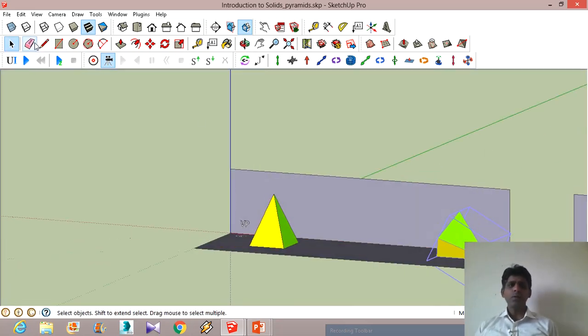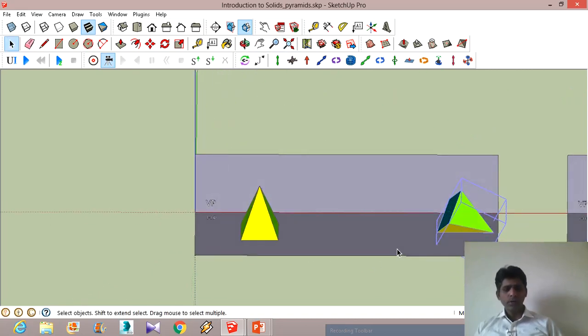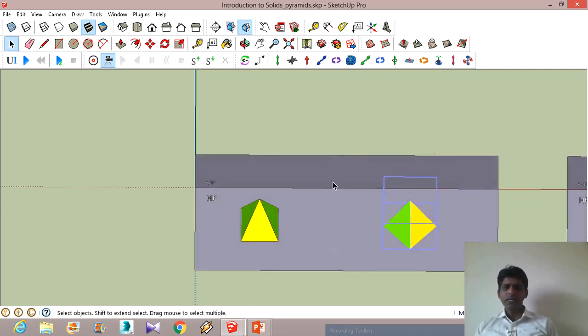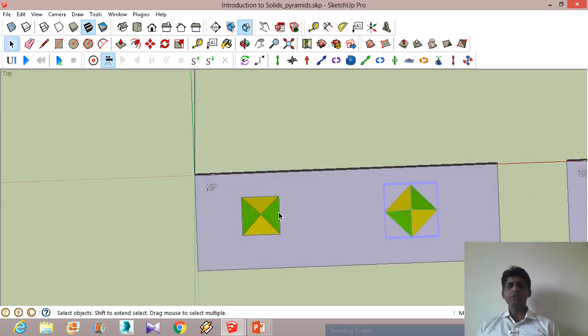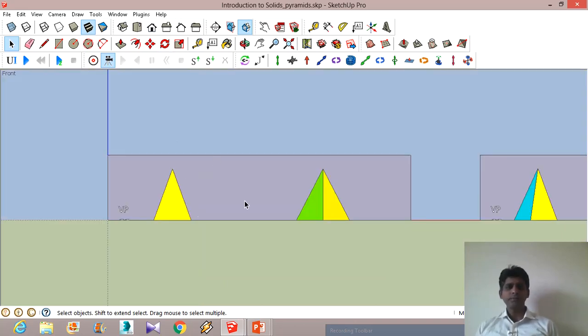So depending on what is asked in the question, we have to select the orientation in the initial view. So whenever we are asked to draw resting on edge or resting on triangular face, we will draw this, and whenever we are asked to draw resting on corner or resting on slant edge, we will be drawing this as our initial top view.